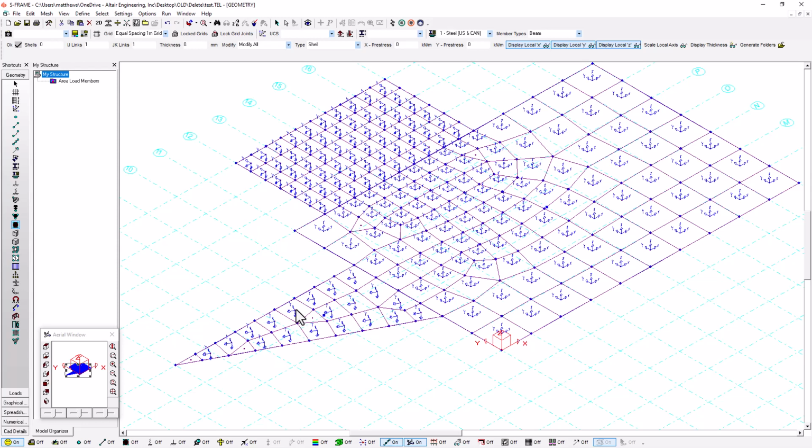Now what I can do is I can say, let's just change this so that all the coordinate systems are in the same direction. And I can use the existing coordinate systems that I already have. In this case here, I just have a global system, which is with respect to this global coordinate system, the x, y, and z shown in red. Or I could create my own coordinate system, which I'll look at later. And what I can do now that I have those is I can use the quadrilateral element tool, which will only adjust the quadrilateral elements in my model, not the triangular elements.